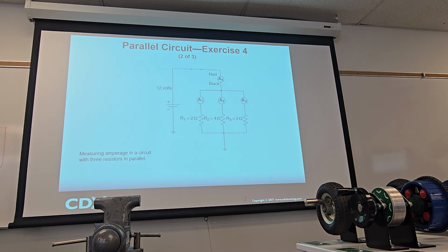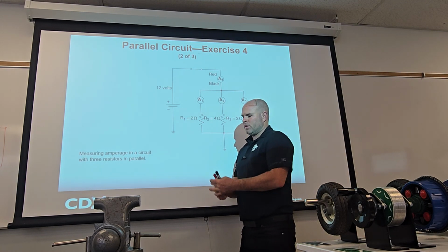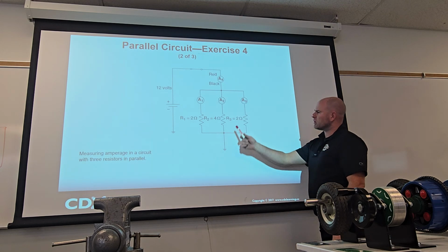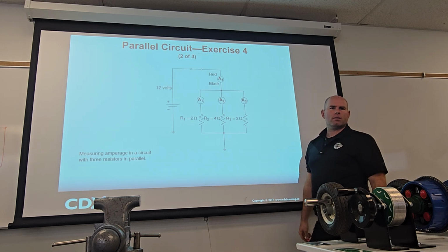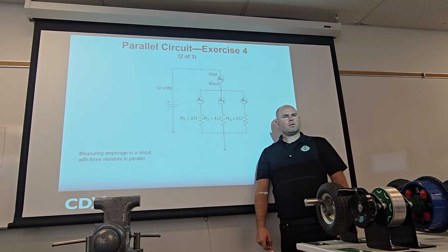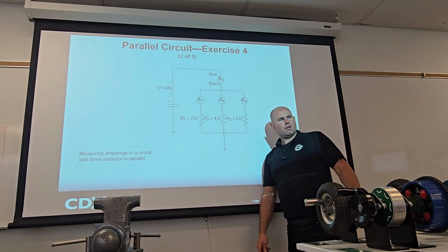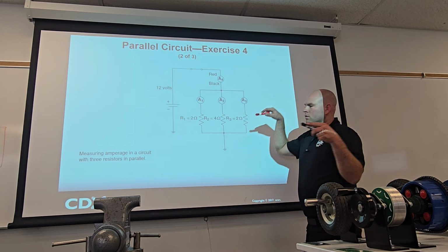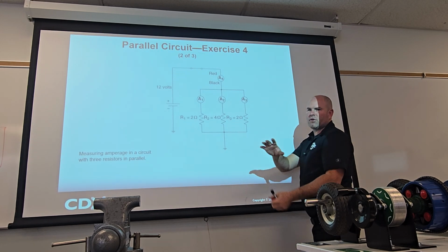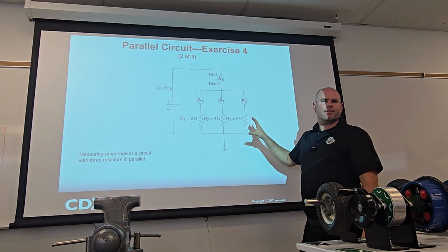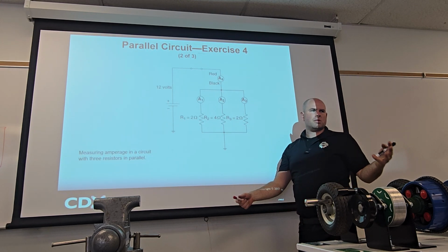Now I will give you a little bonus right here because we're kind of summarizing the theory. If I wanted to measure the resistance of this resistor right here, talk me through how do I do that? Switch it to ohms, click to ohms, I agree. Then you put it right before the resistor, yeah. Like this, boom. Yeah, and just don't forget, you need to disconnect it. Disconnect it and then measure resistance. You're like, oh yeah, it's 2 ohms. Yeah, that's it. Measuring resistance is simple.